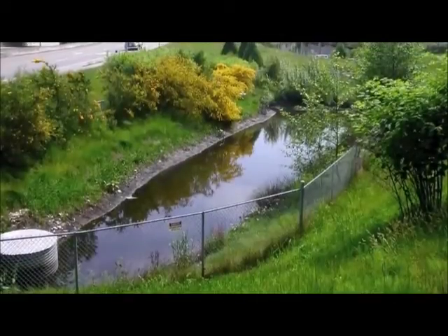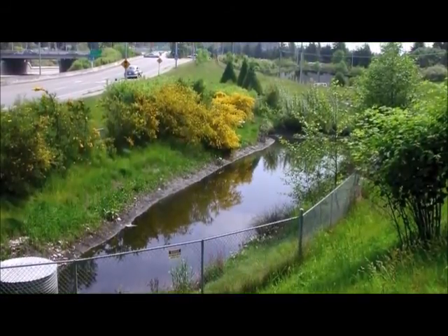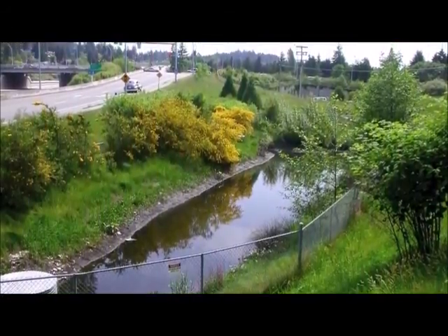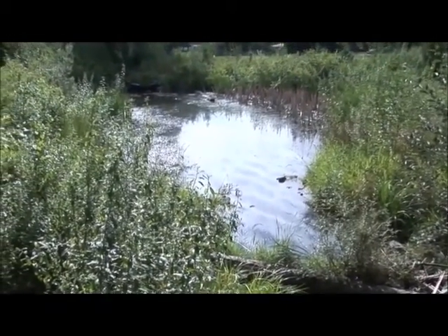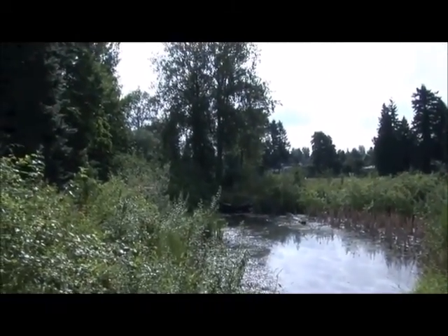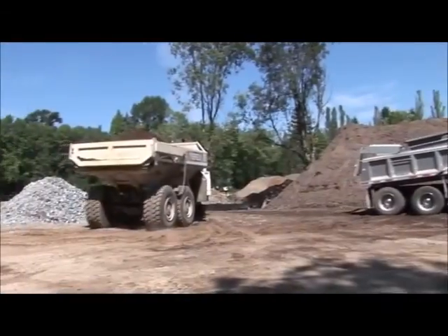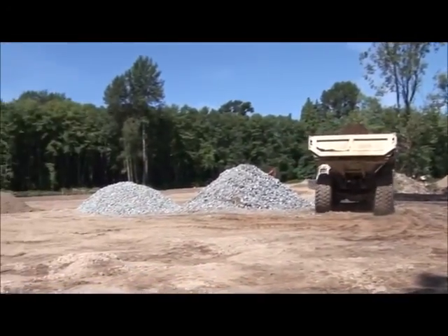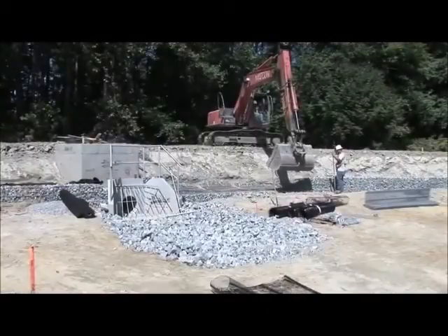Detention ponds and wetlands. Detention ponds can be situated throughout an urban watershed to temporarily receive and store piped stormwater runoff from adjacent neighborhoods. This storage process allows sediments and contaminants to settle to the bottom of the pond before the overflow water enters a water body. Carrie Barron takes us on a tour of a new detention facility still under construction in the city of Surrey.